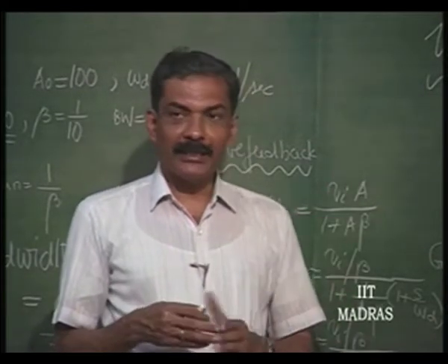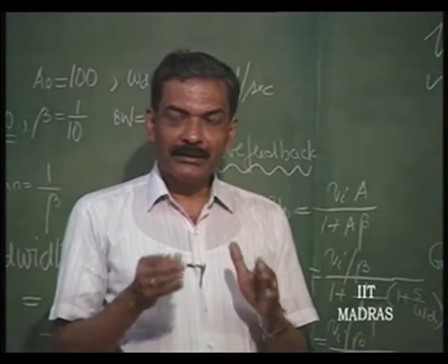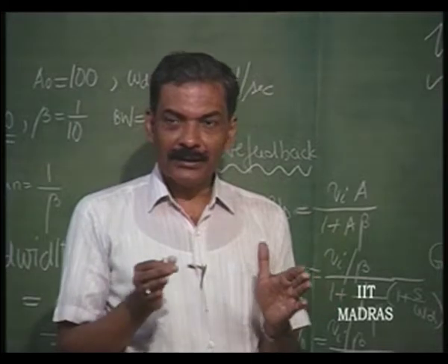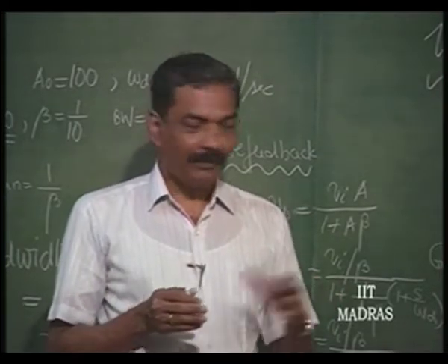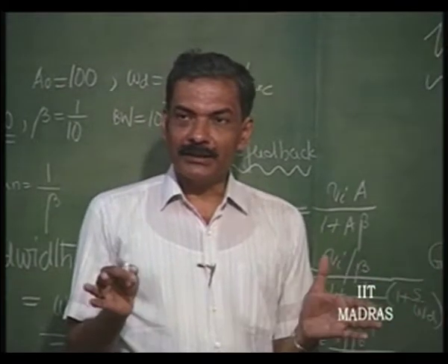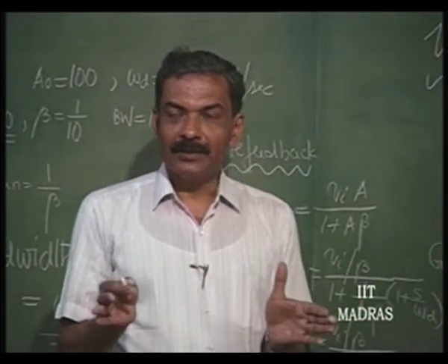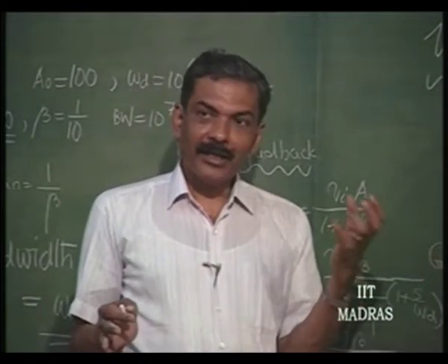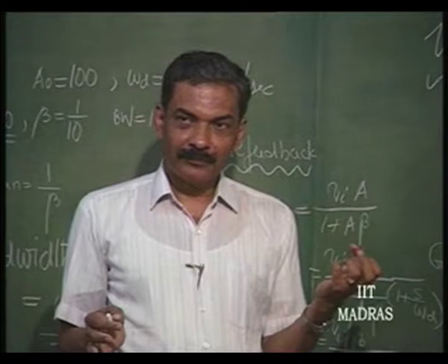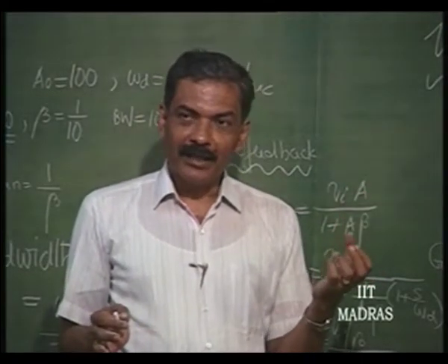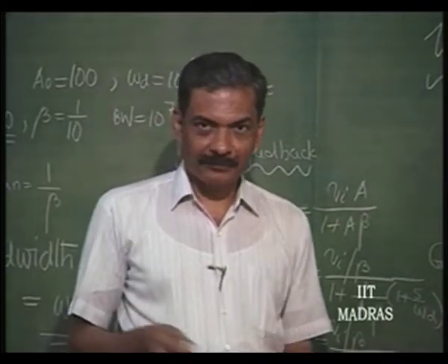For the particular gain that you require, you must just give enough margin so that it does not oscillate. This is the optimum way of providing compensation, so that it works best for the widest possible range of frequencies. So, using an example of wideband amplifier design with negative feedback, I am going to demonstrate this effect.